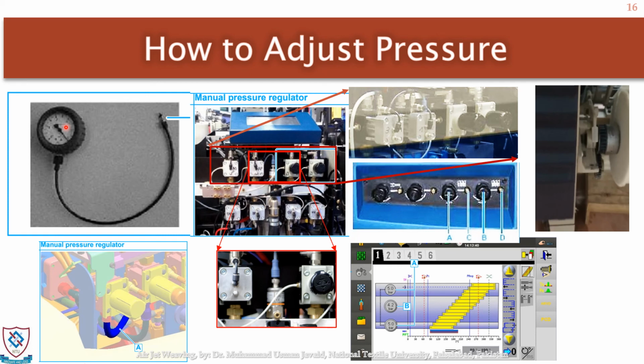And afterwards, once we have adjusted the amount, we can go to the machine panel and adjust the release time of different nozzles, the timing of release. We can extend these bars in this direction or in this direction, or contract them, and that will decide how long the different nozzles will release the pressure.